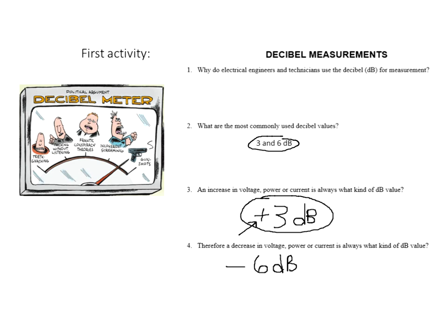But if you hear the word an increase in dB, that always means a positive. But down here, when you're looking at this one, it has a negative sign in front of it, and a negative sign in front of the number always means it's a decrease in the value. But quite often, they'll leave that negative sign off and they'll say you have a loss of 6 decibels. Well, when you hear the word loss, that automatically means a decrease in the number.